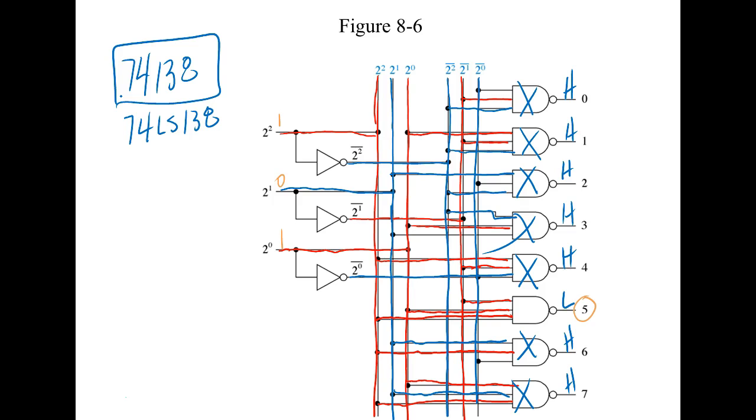I have to come up with a power supply that has the ability to run all the integrated circuits on this board there. So that means I need to know the power required by every guy on that circuit board before I can build a power supply. If I build a power supply that's too big, then I'm wasting too much money. If I'm building a power supply that's too low, then nothing's guaranteed.